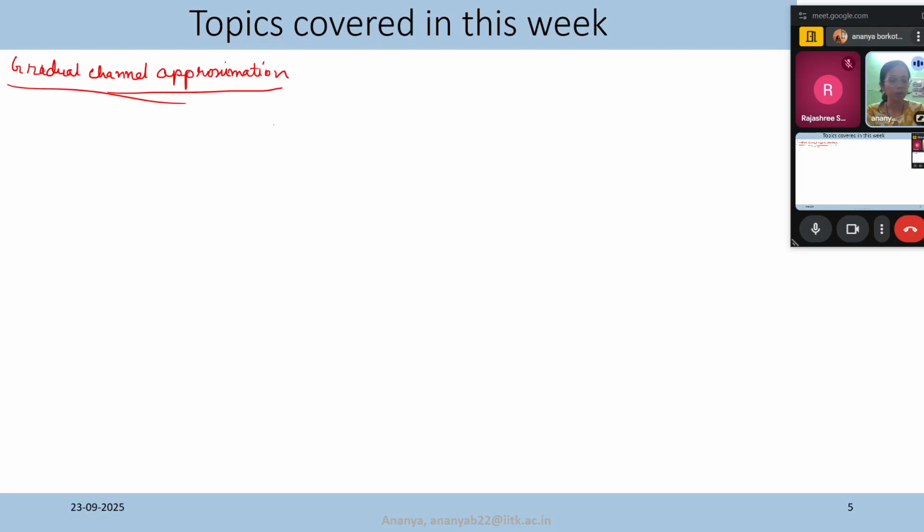If you remember, we have discussed the assumptions and approximations in PN junctions. The current expression, we derived in the PN junction by assuming certain conditions. We considered low level injection. We considered that the minority carriers injected reach the edge of the depletion region. We assumed that the depletion region is completely depleted, right? There are no charges.